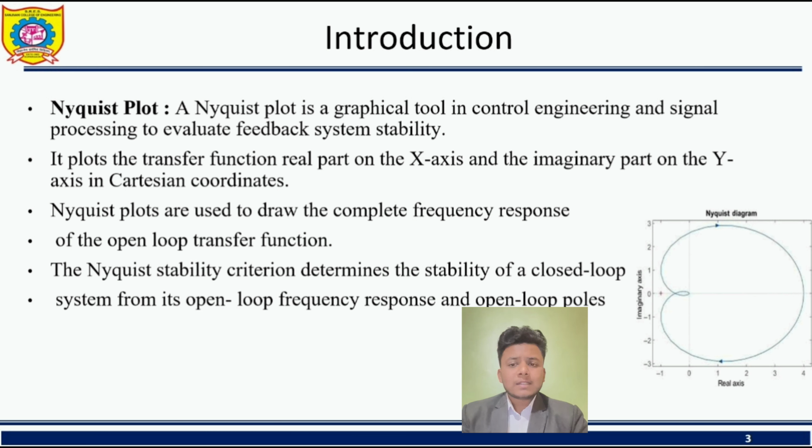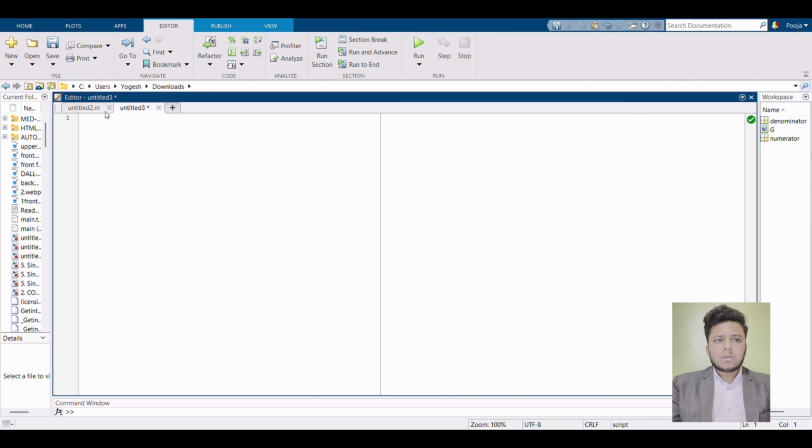First, it helps assess stability using the Nyquist criterion. Second, it provides insights into gain margin and phase margin. Third, it is useful for analyzing systems with time delays and non-minimum phase characteristics. Now we will see the code for the Nyquist plot in MATLAB.